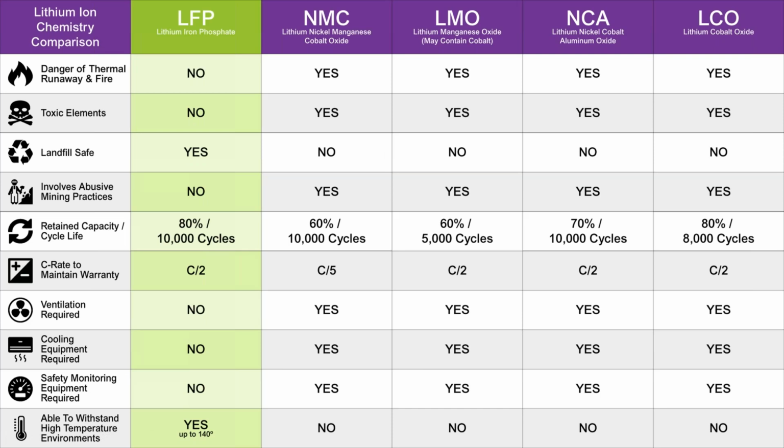For a cottage that is closed for the winter and in Northern Ontario, does it need to be heated? So it's going to depend. This question comes up quite a bit up in the north. It's definitely one of the main questions I get whenever I'm up in Canada in general. If you're going to completely disconnect the battery, so the whole system is being turned off, we actually have an even lower temperature. I believe it's currently negative 20 C for storage, or actually, you know what, I believe it's about to be changed to negative 30 C storage. But if it is operating, then you would need to make sure that it falls within that 0 degrees Celsius. So as long as it can stay there, you're okay. We do have some heating pad options that we can always direct you towards, where the heating pad only comes on if it's tripped by a thermostat, just to get that battery up to a reasonable temperature.